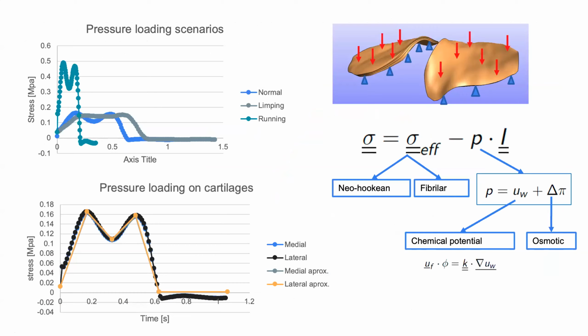Continuing to the second part of the hands-on, we proceeded to employ a finite element analysis to find out what happens at the tissue level. For that, we employed 3 different simulations for normal gait, limping, and running, with the data coming from the previous step. We simply translated forces into stresses by dividing by the area, and simplified to linear regimes for the sake of computational time.